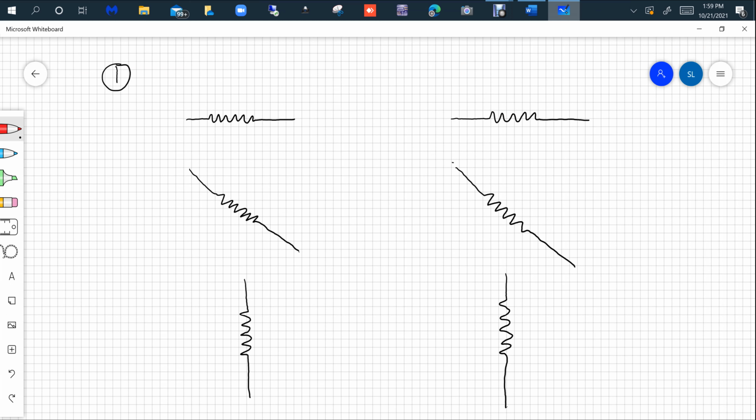I'm going to start with just a simple example here. I have 5 quick whiteboard slides to show you. Most of your circuits are going to consist of resistors and dependent and independent voltage and current sources, but we're talking about passive elements now, which is the resistors in most cases. If you assign direction of current in this direction through a resistor, what you have to do is put a plus on the side of the resistor where current enters and a negative where the current exits. Don't forget, current is the flow of charge carriers.